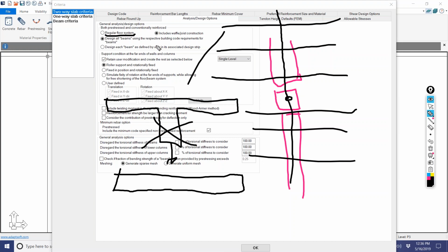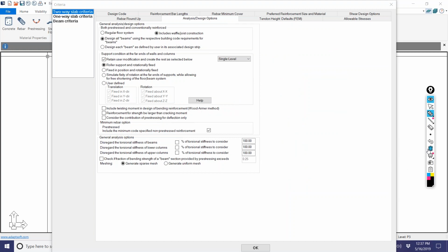So you have to be careful. If you want your beams to be represented as structural beams and this stem to be included as part of this cut that we evaluate in Designer, you either have to make sure you set up the support line so it snaps to at least one beam end. So this beam I would actually move to the center of column, and that's how this model is set up. Or just turn on waffle construction, and that means whenever a section cuts through a beam, the stem is always included in the Designer when we design that. So this is kind of a global setting that we can use for that purpose.